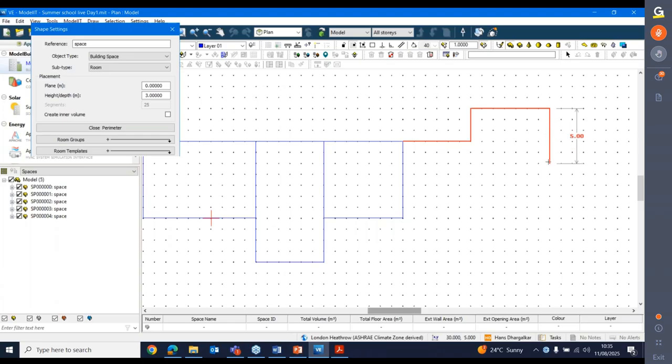Okay, so I'm drawing the outline of the room with separate clicks. If you make a mistake and you don't want to draw that line, you can use the right mouse button or the escape key to unwind the room segment by segment. Okay, so I'm just going to finish the room. You have to finish the room by closing the room off. You can't leave a room unclosed.